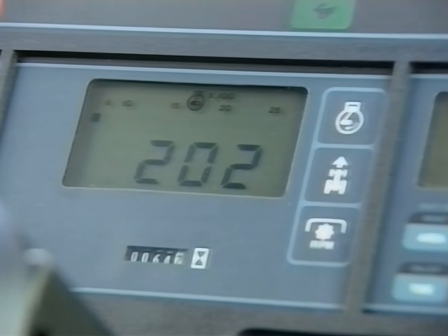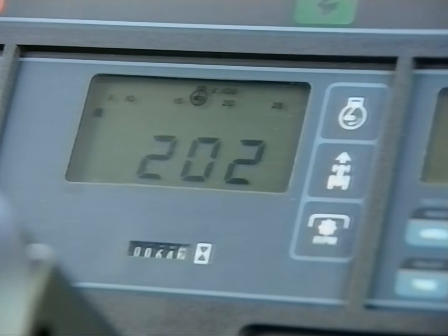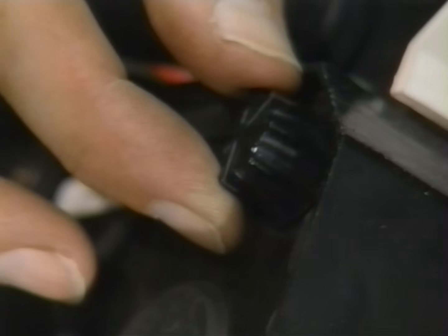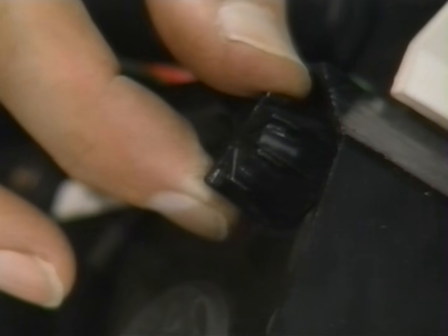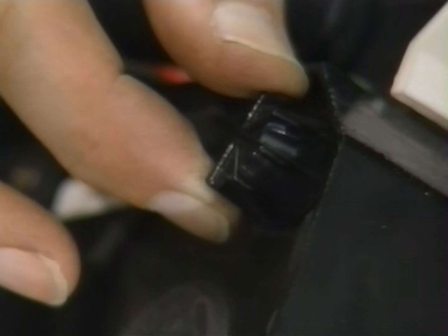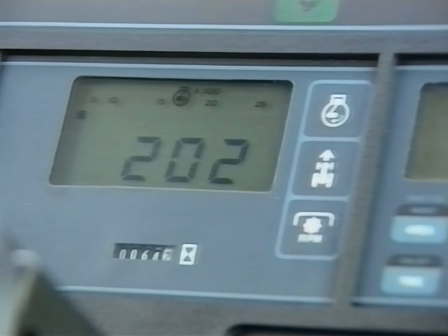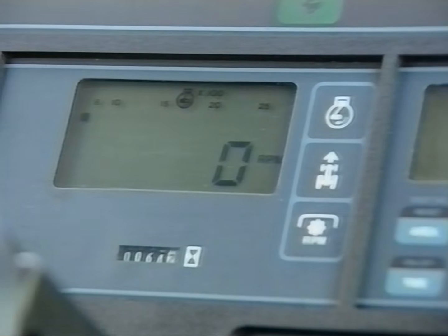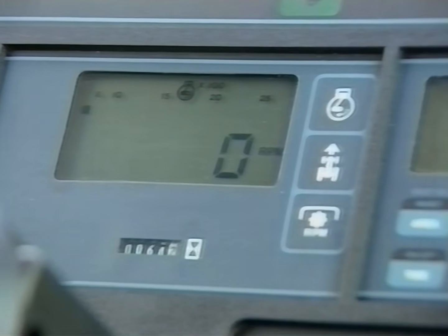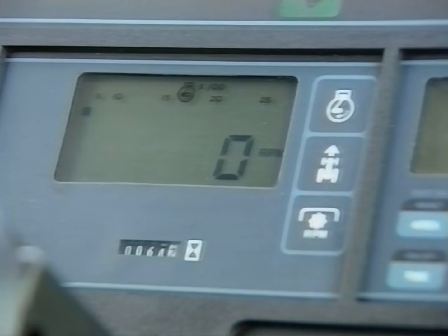be recalibrated. To do this, first remove the 4 attaching screws from the panel to gain access to the calibration knob. Then rotate the ground speed calibration knob until the correct number appears on the central digital display. Once the electronic instrument panel is reinstalled, pressing any of the selector switches momentarily returns the EIP to normal operation.